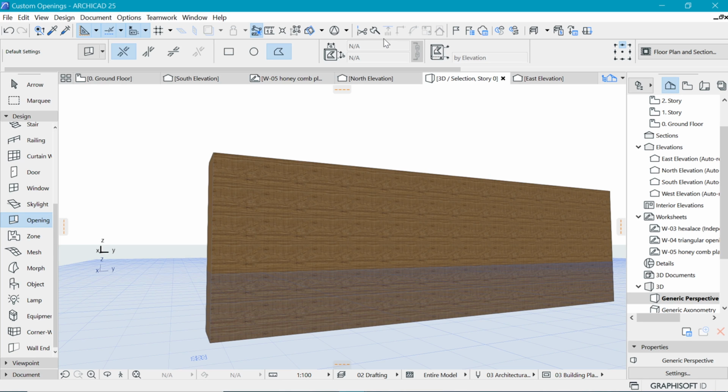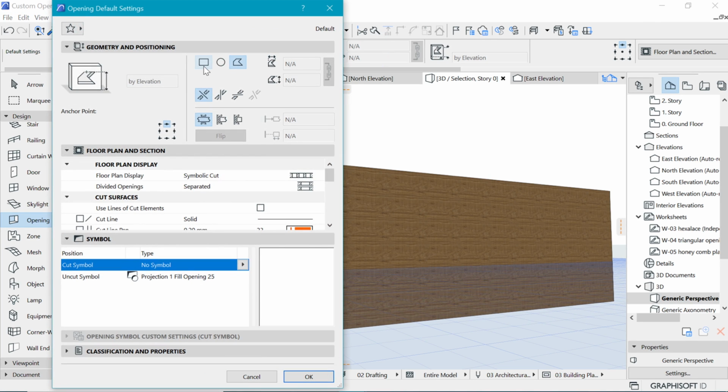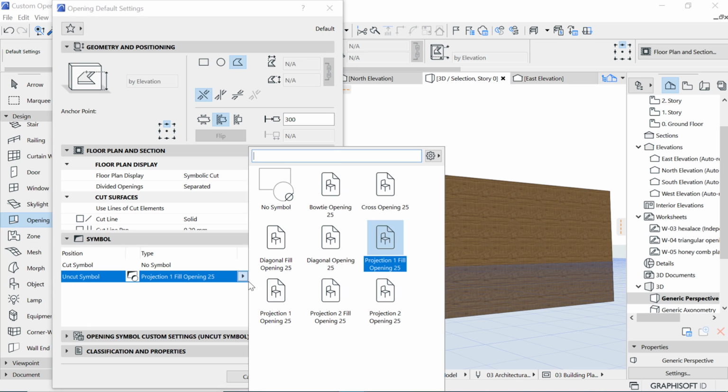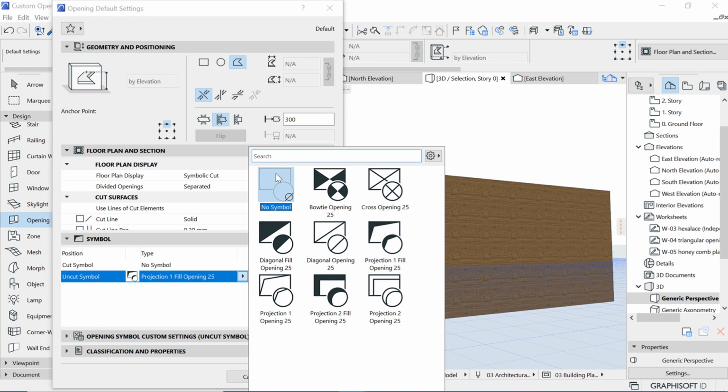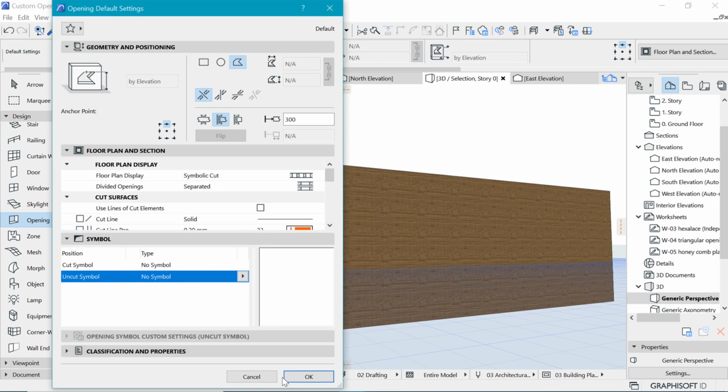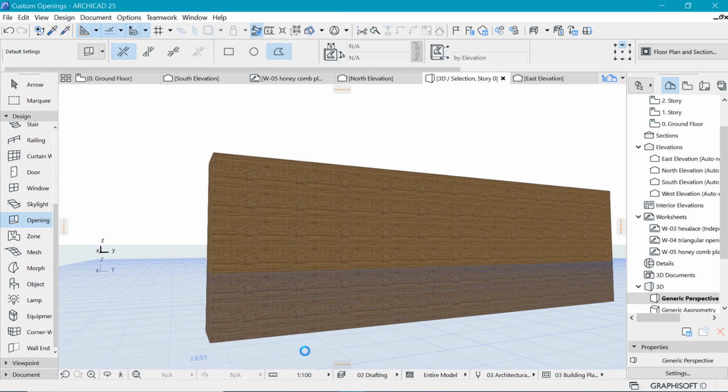So before we do anything, we want to be able to come in here and tell Archicad that we need this second kind of shape where we are just doing a niche, and I'm going to make this 300 back to have it 600, 700 deep. And even here you can choose what shape it should look like.